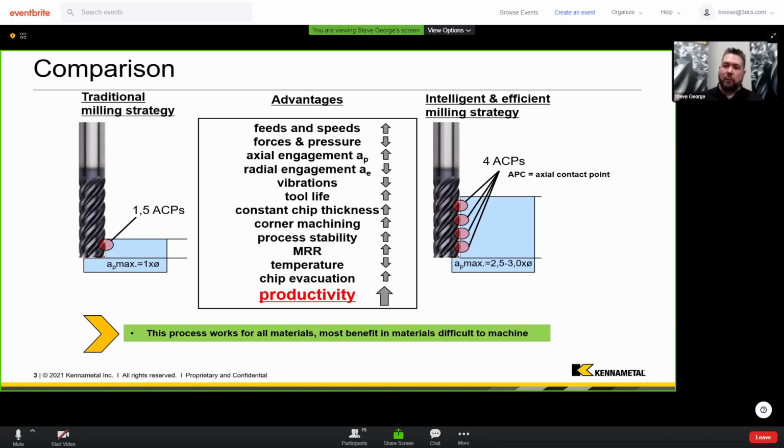Print it, and there are now features that I need to mill. Typically on an additive part, you may be choosing to mill some of those features that have very small corners, and those very small corners may call for a very small end mill. And so now when I compare the size of the end mill that I can use based on that cut, guess what? It's now a roughing cut.